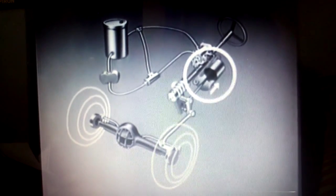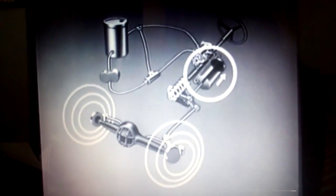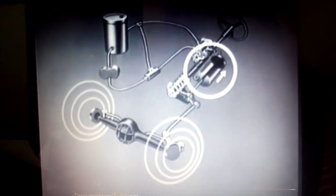Now as you can see, this is the power cylinder. When the piston in it moves to one side, the wheels are steered to one side, and when it moves back, the wheels are steered to the other side. This assists the user of the car in power steering. Now if we make a hydraulic arrangement in a block diagram, it can be shown like this.